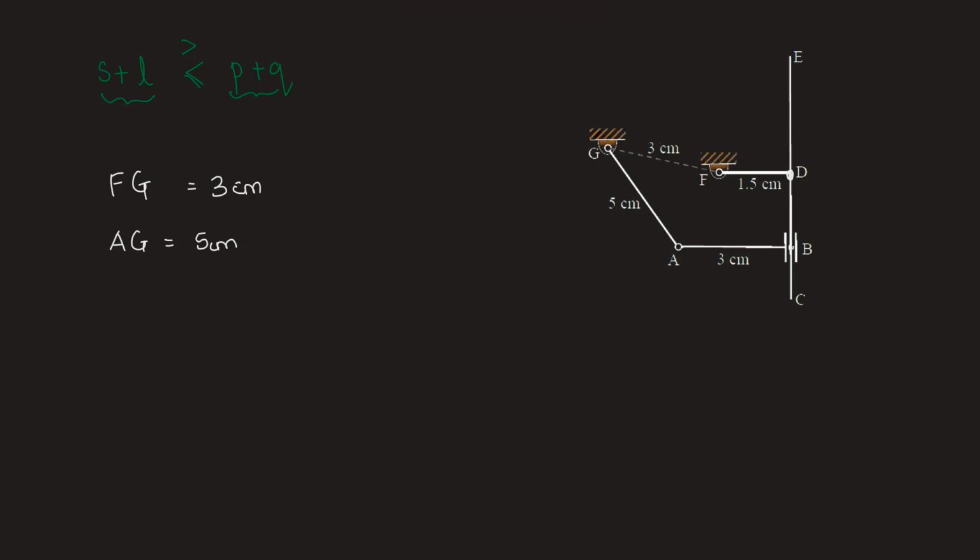So we can take a joint H which is located somewhere here at infinity for this link. For the T link CDEF, when the movement takes place, that is when link AB slides along the T link, this is nothing but that revolute pair again, which is H. As this point H is one and the same at infinity, these two links are going to meet at infinity.